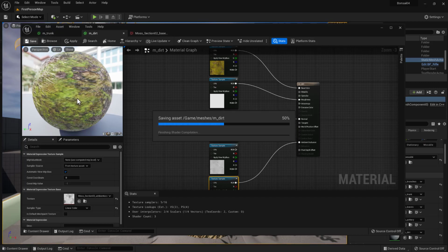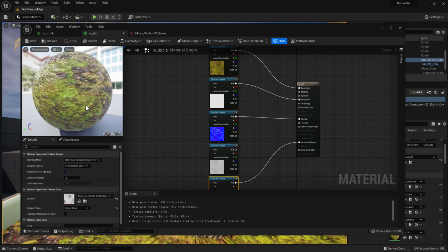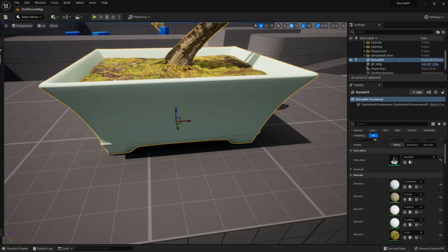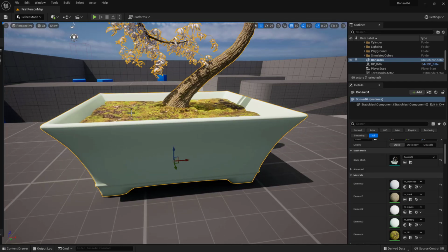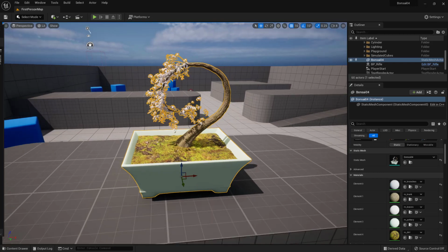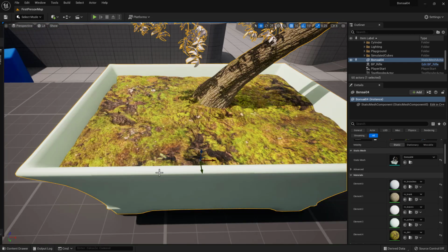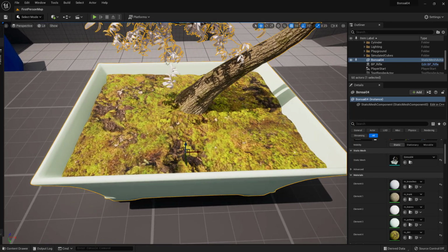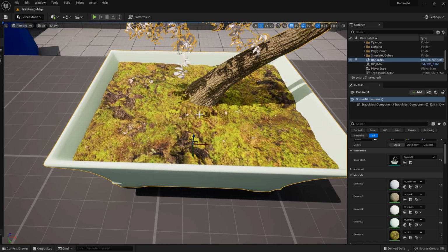It looks pretty shiny. Maybe I need to look at some of my settings here. So let's look at this now. Select that, hit F. You can then rotate around it, and I can see what it's doing here. So that's not too bad. I'm seeing that it looks like there might be a little texture stretching in here, so I might have to go and relax that a little bit, do an unfold or something like that.